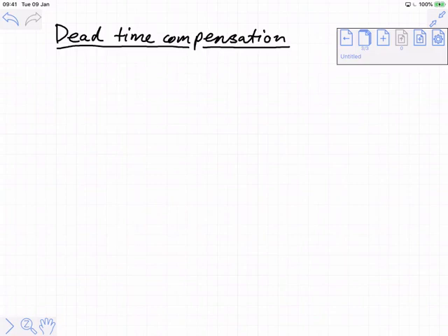We will always start with quote-unquote normal feedback control being the base of any kind of control system that we're going to be working with. And then we're going to layer on additional helpful things. The first thing that we incorporate is measure as early as possible.